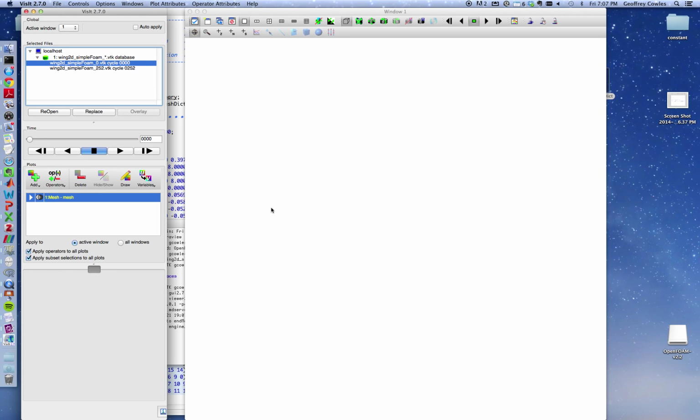It's shaped like a C. A C grid is a typical way of meshing an airfoil in such a way that you can resolve the boundary layer, not only the boundary layer on the wing, but you can resolve the wake. You have this region here to be able to resolve the wake as well. It's a C grid. So I'm going to delete that.